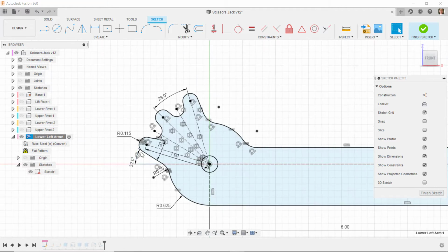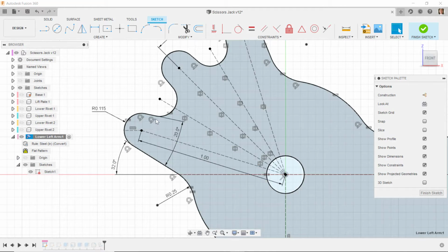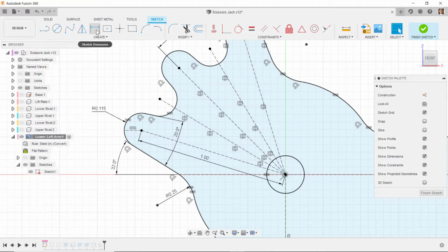And then I want to check the angle between here and here. See, if it's symmetrical, this should be 10 degrees from here to here. So when I attempt to dimension that from here to here, I get an angle of 5 degrees, not 10 degrees. Now that bothered me when I created the part, that I didn't have to add a symmetry between this line and the line of symmetry, but I didn't double check it, so I should have double checked it when it bothered me.